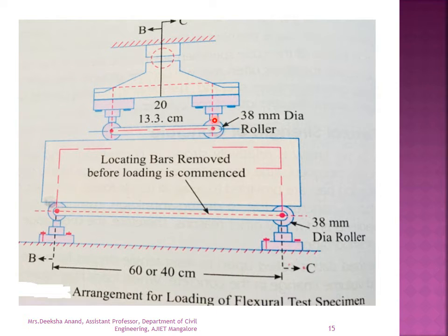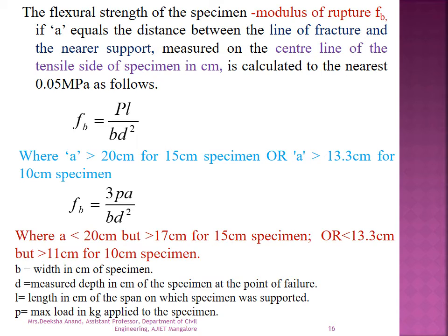All the rollers are of 38 mm diameter. Arrangement of loading of flexural strength specimen, and here the load is applied until the specimen fails.